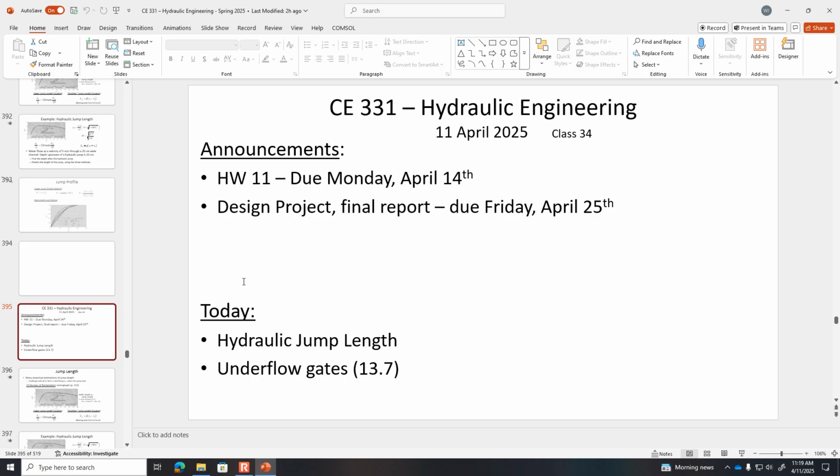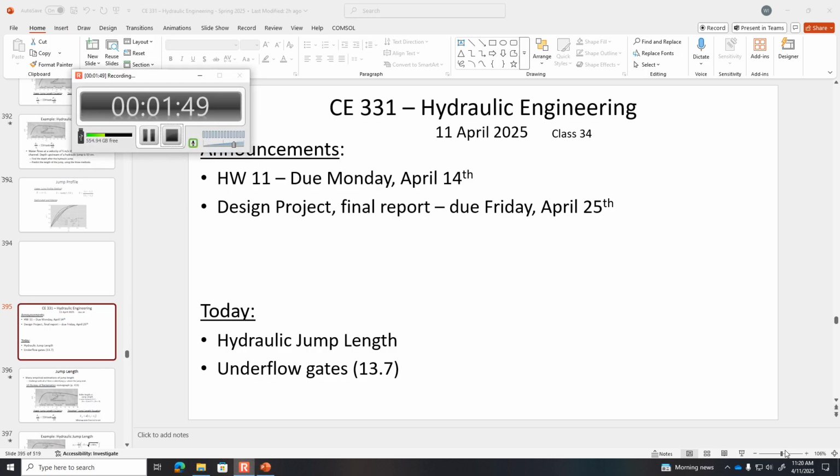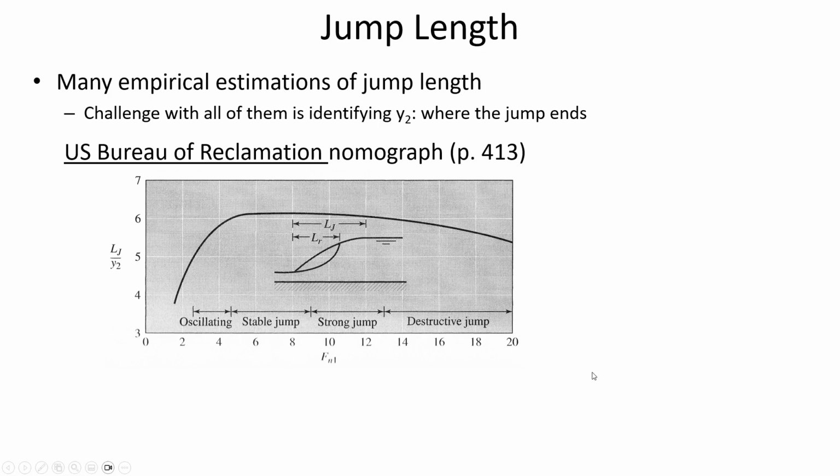So usually the way that they do that is they would have a scale on the side of a flume, send the water through the flume and then see how deep the water is, or they have ultrasonic sensors that acoustically send a signal down and measure the depth of the water. But you'd have to calibrate a little bit to know the appropriate location to measure the depth in order to have the correct flow rate. So generally, if it's a standardized design, there would be a certain point that you'd measure the flow depth at to use as the basis for determining the flow rate.